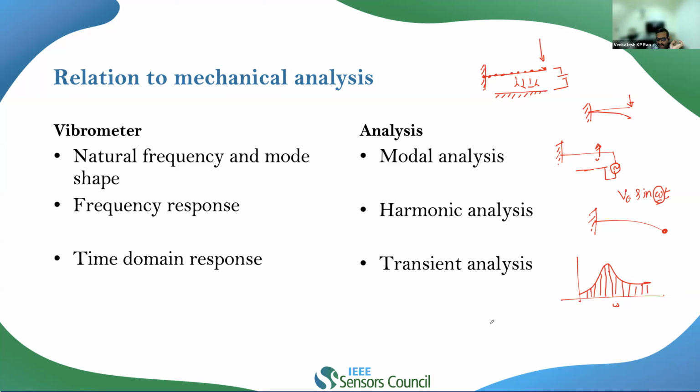Now, whenever we have a frequency response like this, if you do the peak picking, the frequency corresponding to the peak is nothing but your natural frequency, correct? And if you take the 3 dB points and drop them down, then I will basically get the bandwidth of the structure.